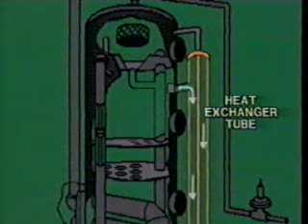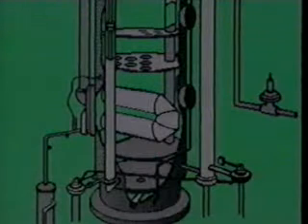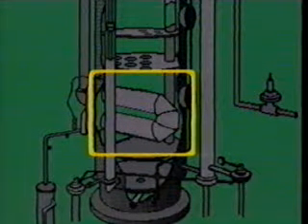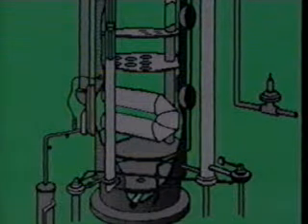The weir box provides a level-controlled, open-top chamber for collection of oil. After the oil reaches a preset level, it leaves the settling section, flowing into the heat exchanger tube. Gas is vented through the pressure equalizer to maintain consistent, even pressure inside the vessel. Located between the settling section and the free water knockout section, the heating section applies heat to the emulsion.